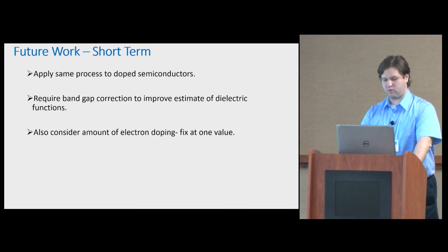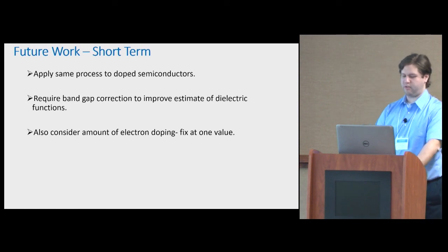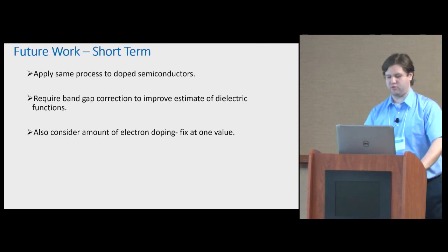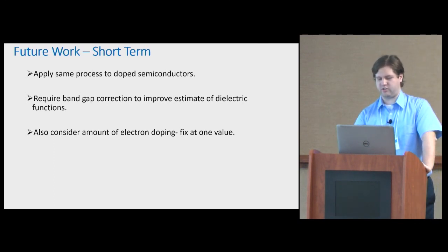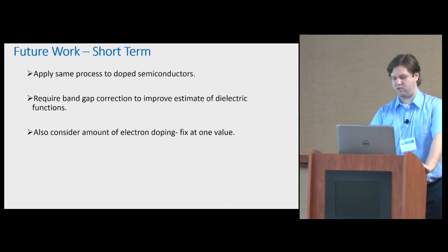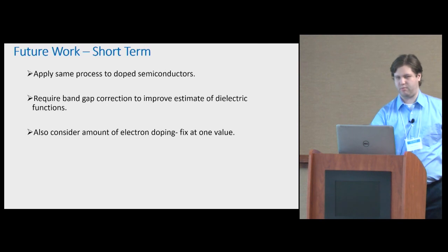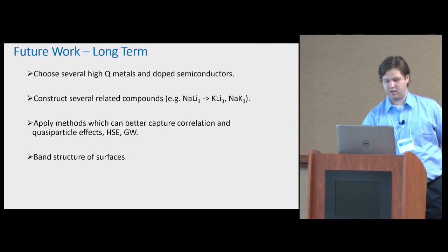So future work, in the short term, we're going to apply much of the same process to doped semiconductors, but this will also require band gap corrections due to the DFT error in the gap for dielectric functions, and we'll also consider the amount of electron doping, which will be fixed at 1 value for the time being.